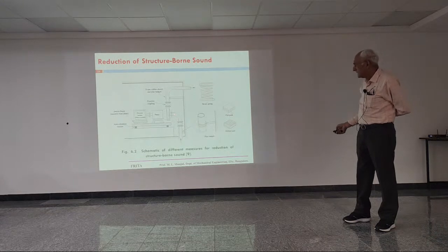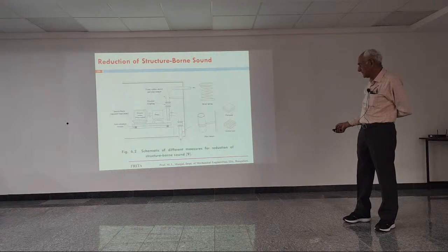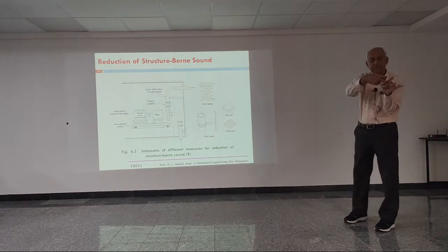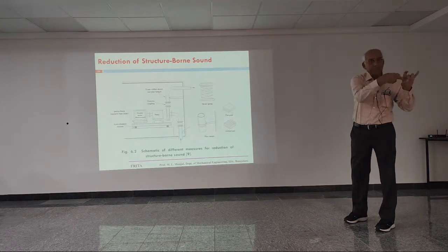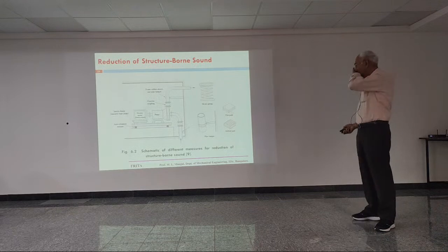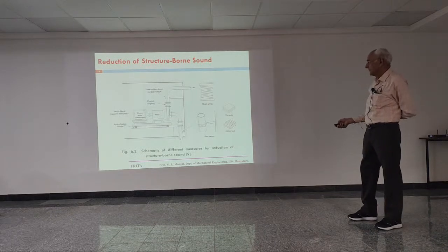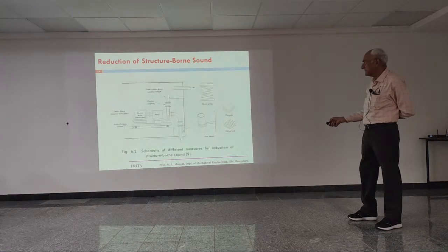Now, please note here that this is coming here and it has to be supported, and this is what I have extended here. So this is called a pipe hanger. It is supporting like this, and then we have a sleeve, and there we have the damping gaskets. Then the same thing here on the discharge side.